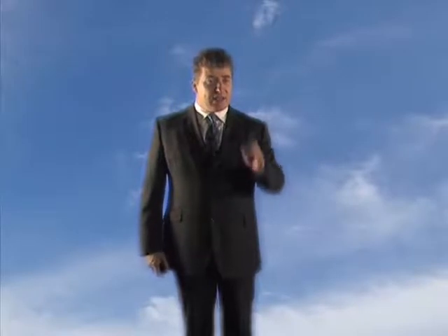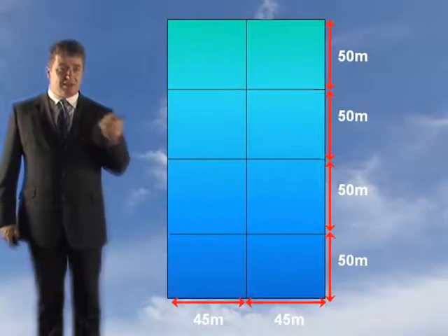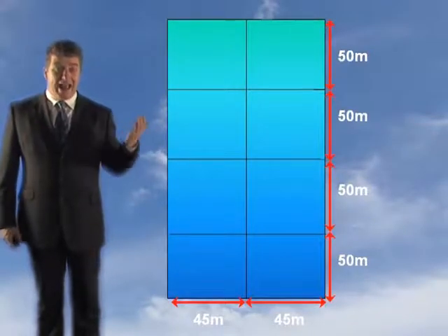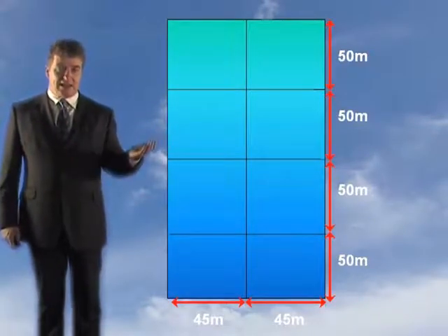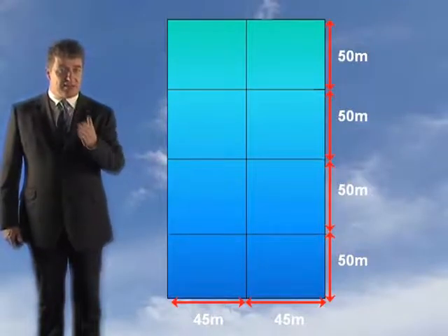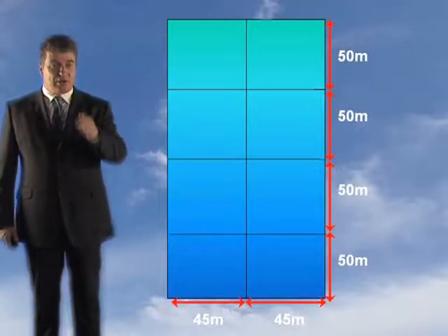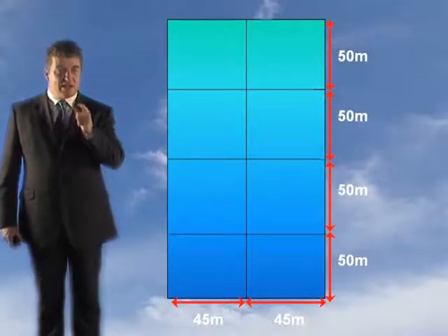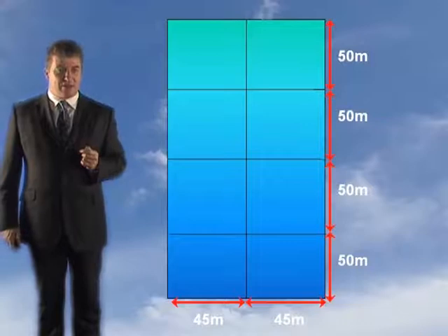However, you've got another rule to satisfy. Don't forget the 60 metre rule. You can't have any dimension longer than 60 metres. Based on the parameters, as you can see here, we need at least 8. You might need 6 to meet the area requirement, but based on these parameters, you can't have one more than 60 metres long. So in this case, we're actually going to have to increase it. We need 8 reservoirs. That's what you should have worked out, 8 reservoirs.